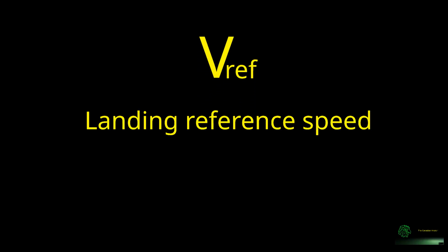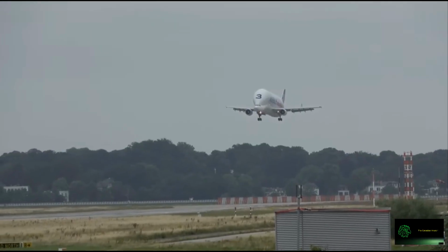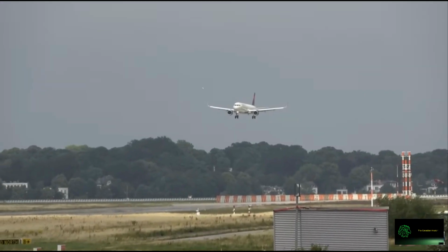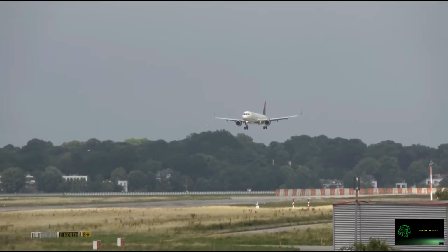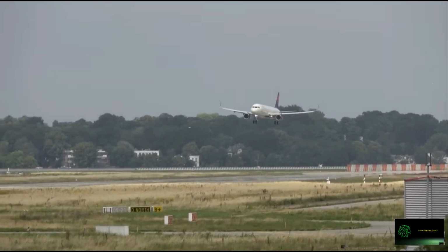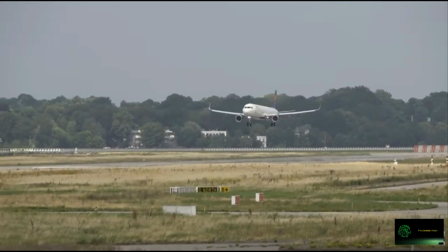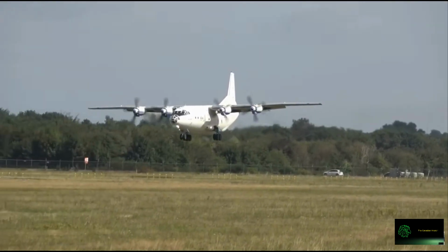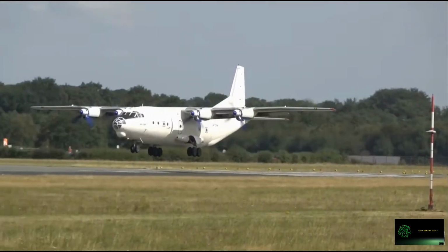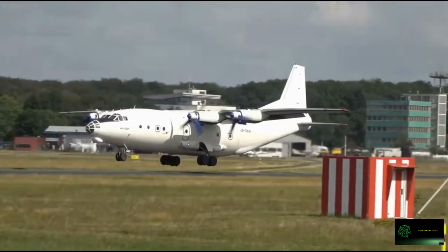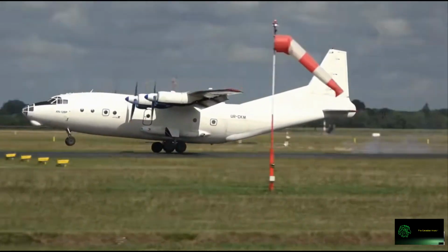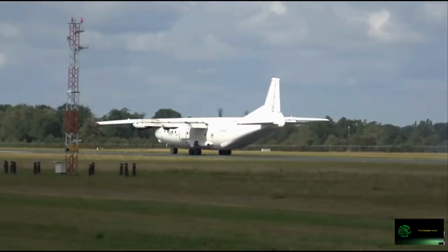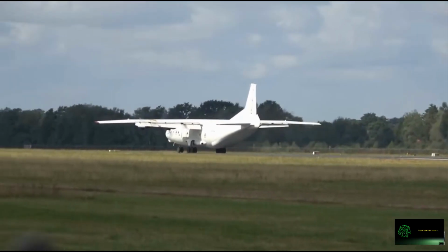VREF, landing reference speed. It's the target speed flown on final approach during landing. It provides a safe margin above stall speed while allowing the aircraft to touch down at the correct speed and distance. VREF is calculated based on aircraft weight, configuration, usually full landing flaps, and sometimes wind corrections. It is not permanently marked on the airspeed indicator. Instead, pilots compute or obtain it from performance data before landing.